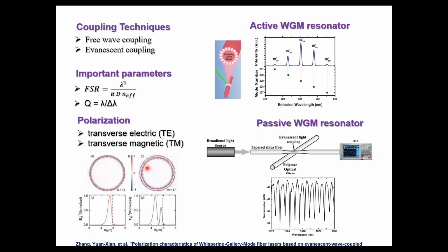The coupled electric field oscillations, you can study and plot them, and number the order of the modes using the asymptotic equation, in terms of the azimuthal mode number or the radial mode number, which order of the mode is currently oscillating. That can be easily plotted.